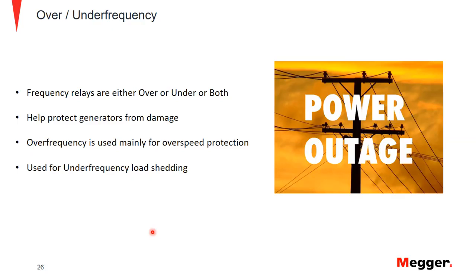And then when a major generator drops offline, I think there were some blackouts that everybody's heard of that have happened over the years. When one drops offline, it's not good. Of course, it becomes this cascading effect. And with frequency relays, this will help mitigate these by specifying which breakers to drop out from load, so we can still maintain some type of system stability, and then we will add load as we go to get us back up to where we were before the fault occurred, or whatever that instance was.